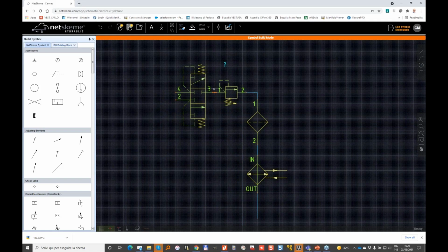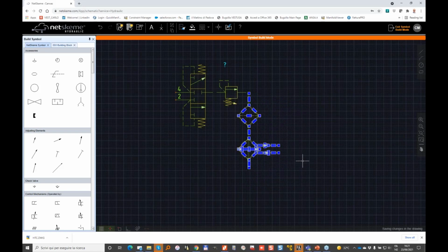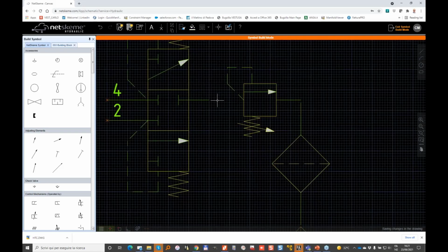Usually it's better not to have connection lines in a symbol, so here I just simplify my geometry. I don't need to have it large. I can simply make it smaller. So let me select. Always with arrow keys, it's much easier to work by using those items.